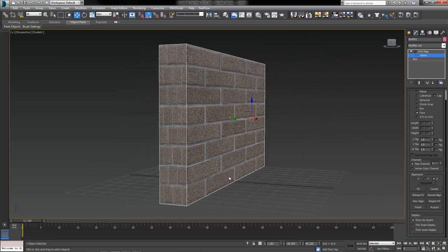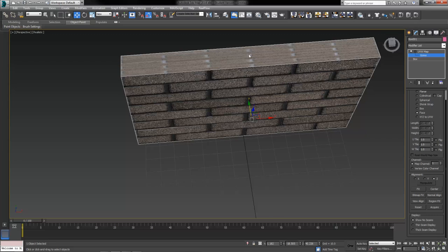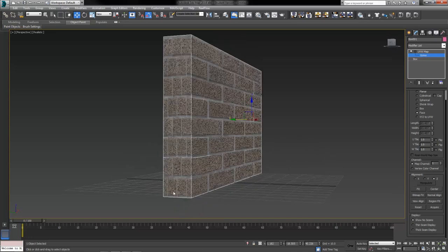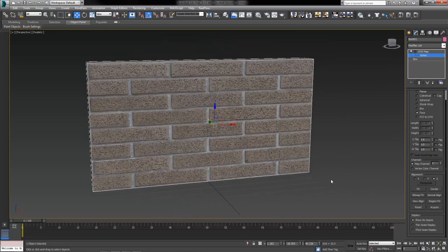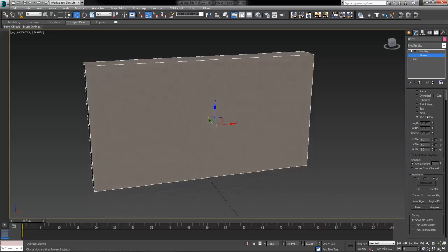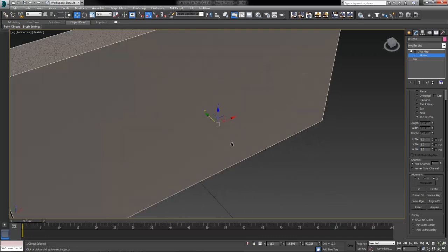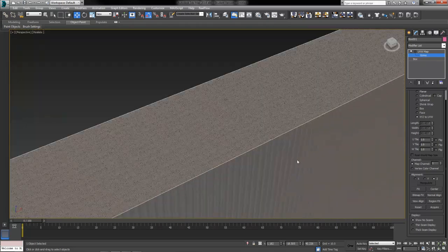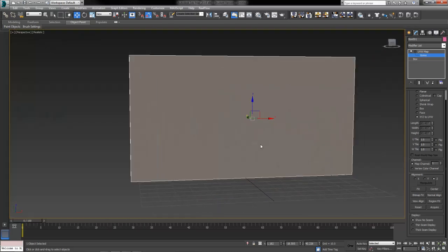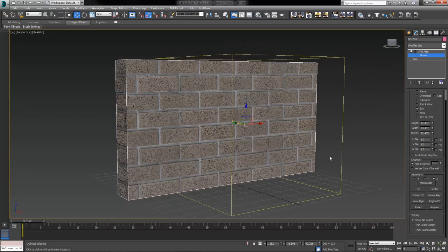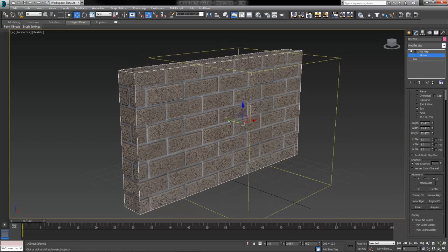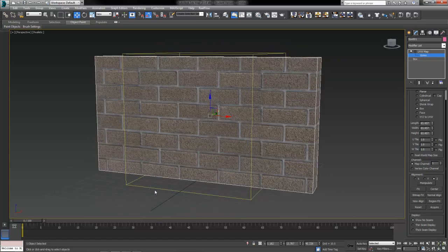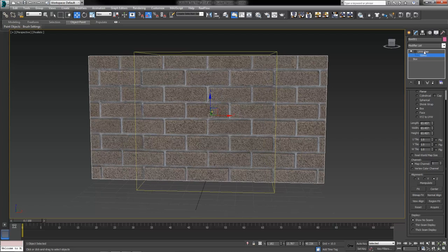Face map will put that picture right back, just like default almost, without the UVW map modifier, just projecting that one image on every single face, no matter whether that face is squished or squashed or not. And then the XYZ to UVW mode, which is going to put those textures based on a world scale rather than anything else, and very rarely is that one very useful either. But for the most part, we can adjust these things based on what the object is similar to in the real world. For a brick wall, our box shape works absolutely perfectly.